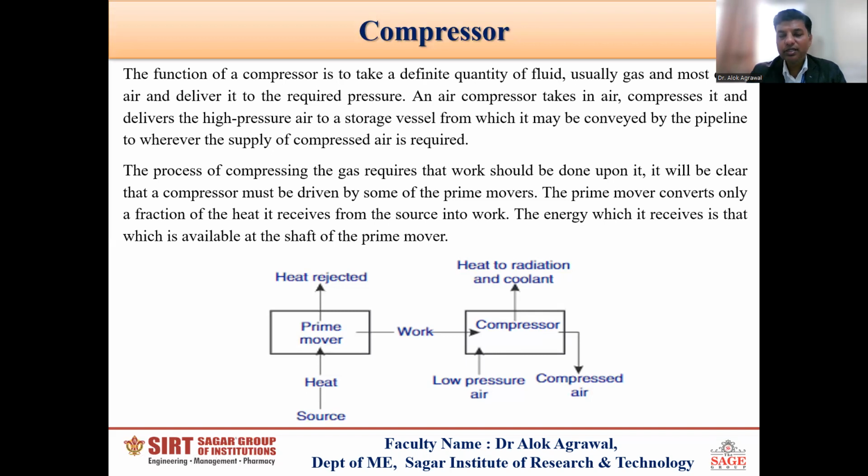And we know that when temperature increases, it tries to increase the volume of the gas, and once the volume increases, it tries to drop the pressure. So a coolant is very much required in a compressor so that though the pressure increases, the temperature remains within a desired limit, so that more compressed air can be stored in this storage vessel. So this is how a compressor works.